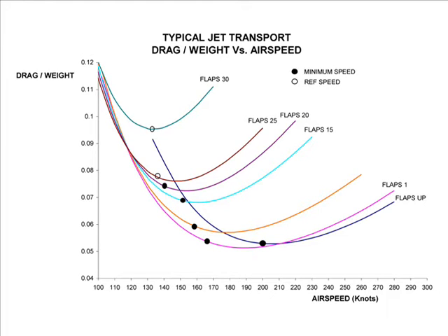This means that if an airspeed error occurs, it will not be corrected automatically. To correct an airspeed error in this flat portion of the drag curve, it is necessary to overpower or underpower, wait for the desired airspeed, and then reset the correct power setting. This is second nature to military pilots that were originally trained on jets, but requires conscious thought during jet training for civilian pilots initially trained on propeller-driven light airplanes.